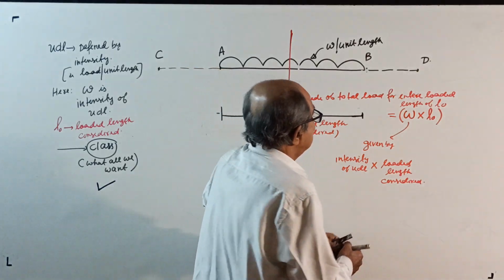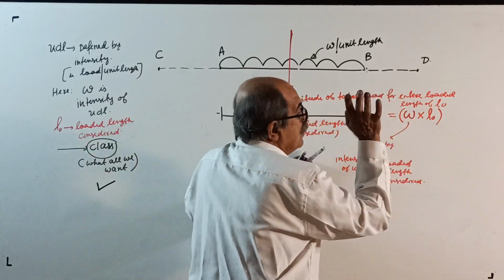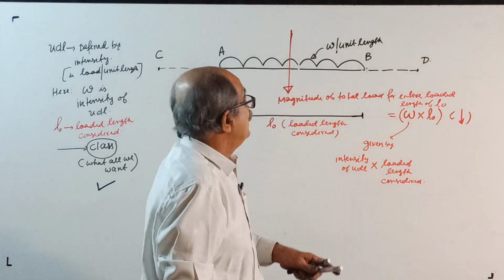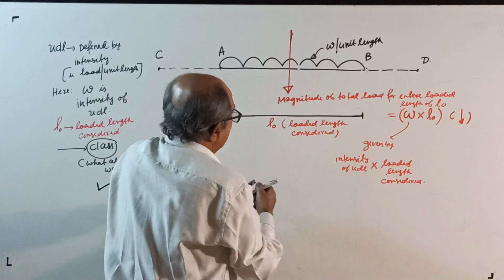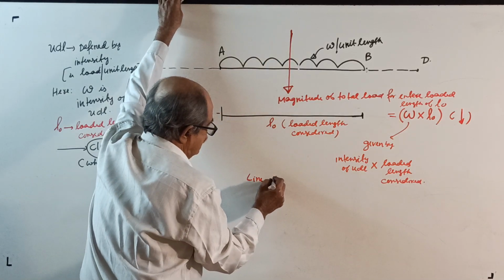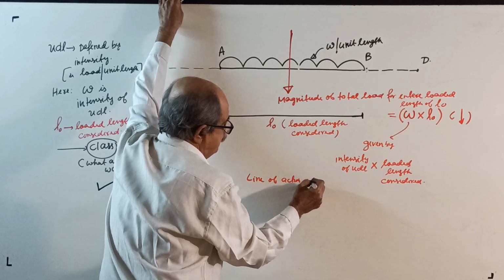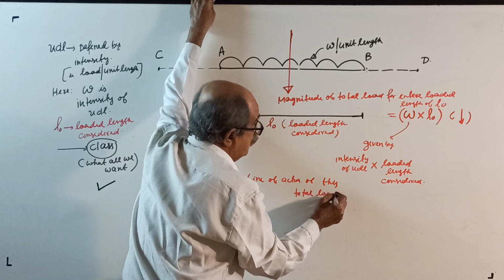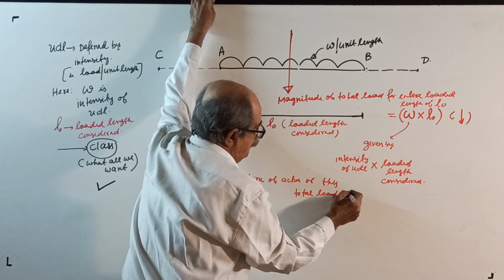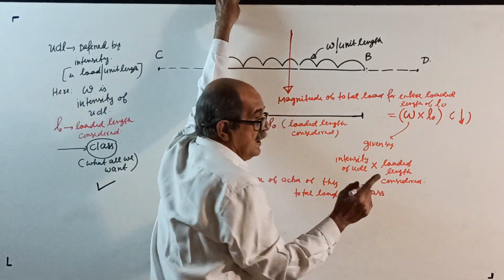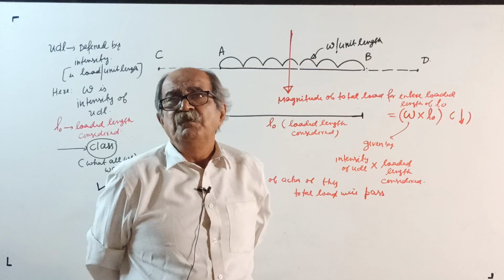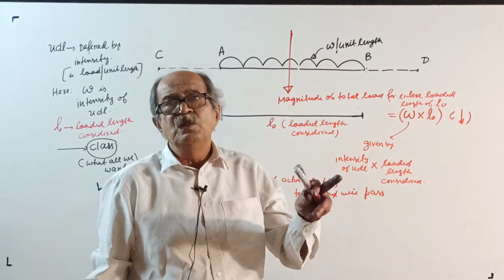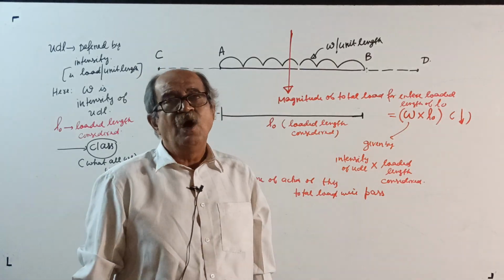This is the load. Now, magnitude over. Direction, you can write here only, vertically down, over. Now next, where is line of action? Right here. Line of action of this total load, that is already I told total load, WL0 load, will pass. Again I told you, if you represent the loading by a diagram, line of action will pass through centroid of the diagram for the loaded length considered. But here we are not drawing diagram.